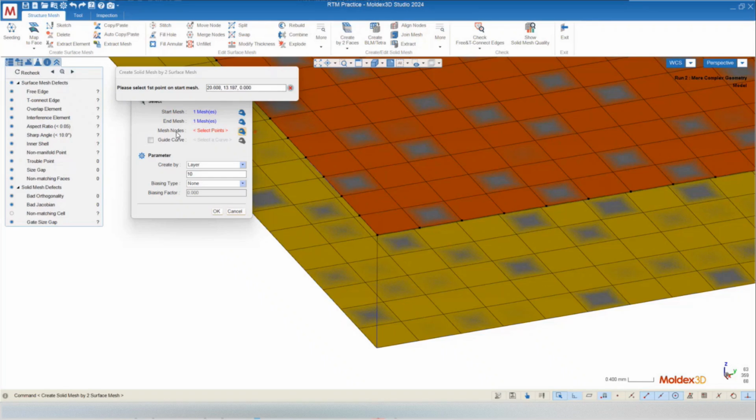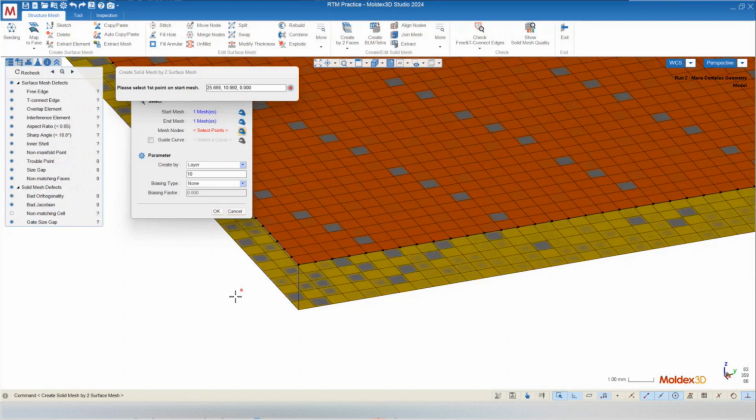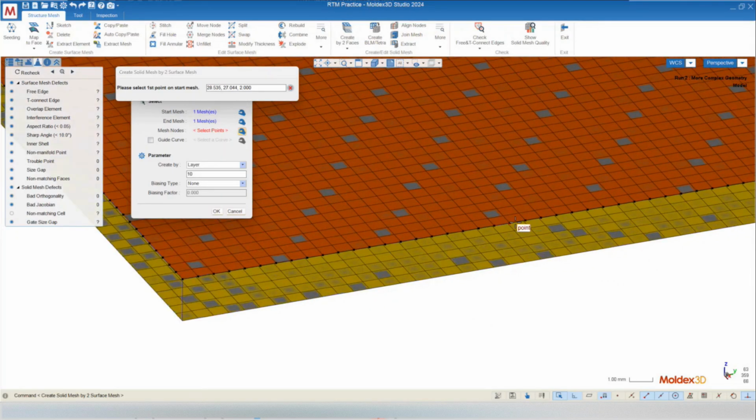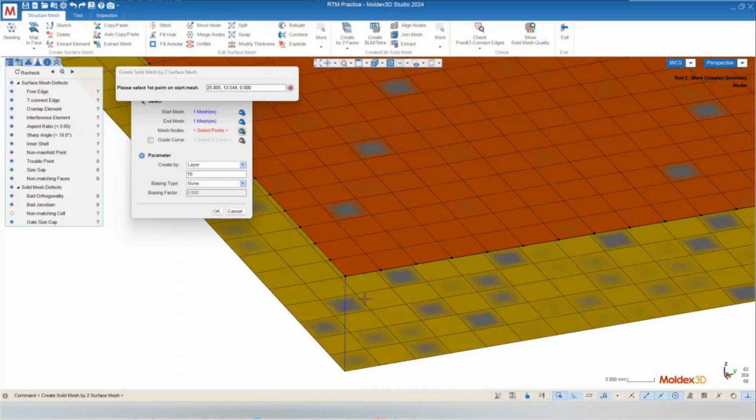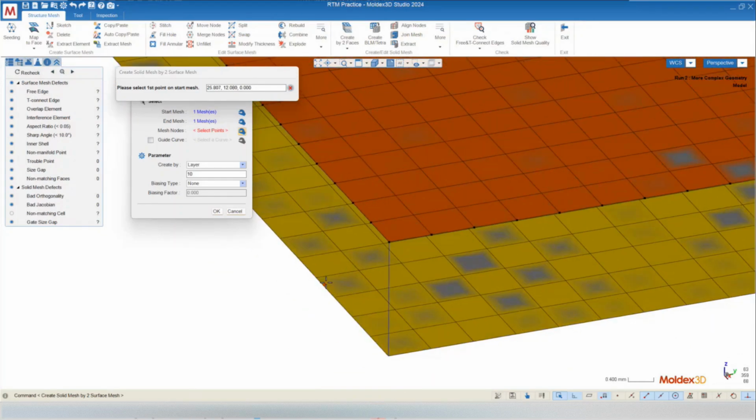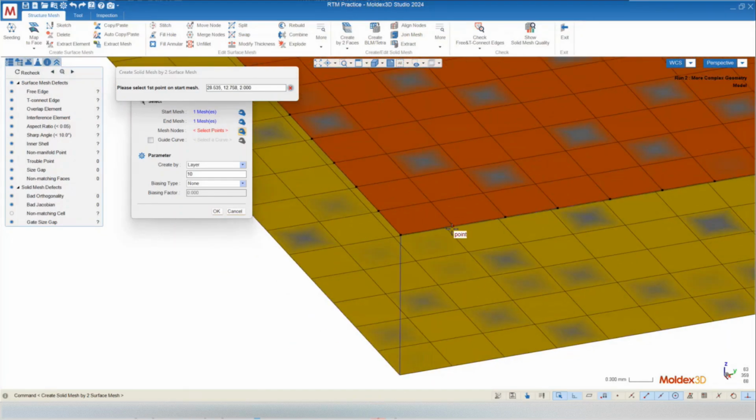All right, so what that's going to look like is I usually use the corner just because it's easier to identify. If I use somewhere in the middle, it's going to be difficult to find those exact 3 points on this mesh. So usually I use the corner just to make things as easy to identify as possible. And what I do is I usually take 1 point off of the corner as my first point. My second point is the corner itself. And then the third point is 1 point in the other, or 1 node in the opposite direction.